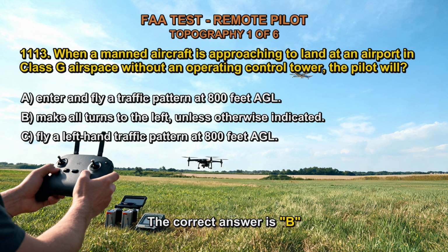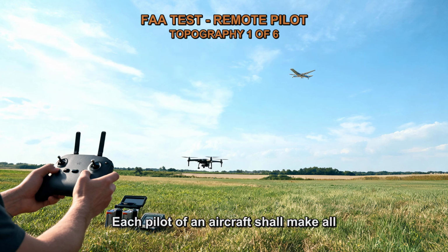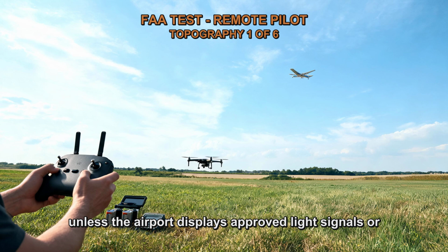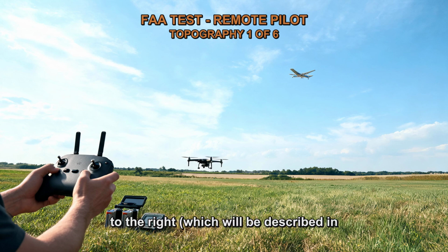The correct answer is B. Each pilot of an aircraft shall make all turns to the left when a manned aircraft is approaching to land at an airport in Class G airspace without an operational control tower, unless the airport displays approved light signals or visual markings indicating that turns should be made to the right, which will be described in the Chart Supplement US.